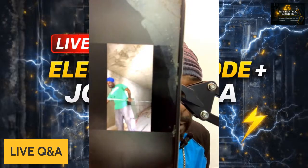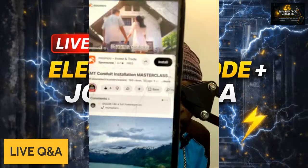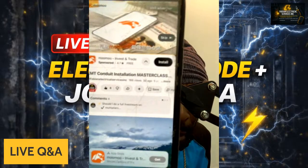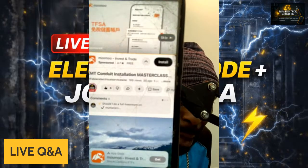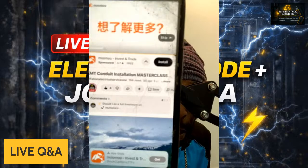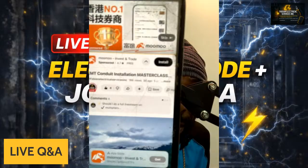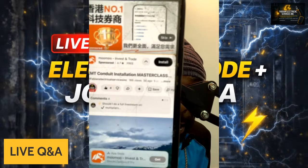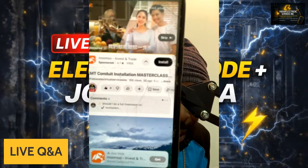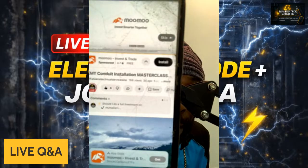It's either going to be a 10 degree, 22 degree, or 30 degree bend. So an offset is made up of degrees and measurements, and you simply need to take your measurements, Jamal, and translate them into real world job site installation, and apply it to the bender that you're going to be using to make your offset.